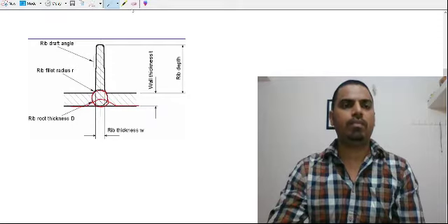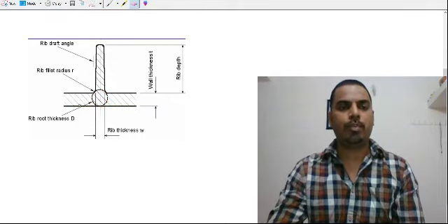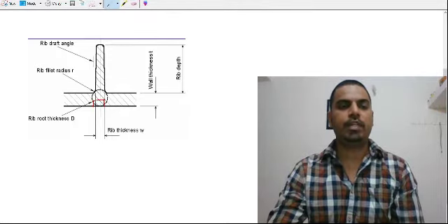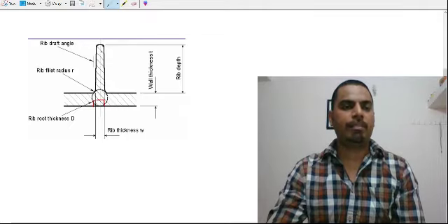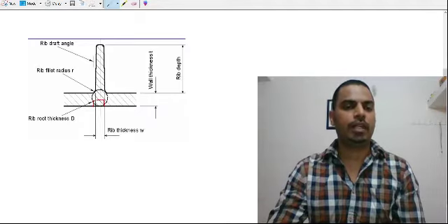One of those options is to provide a groove or a dent at this location, like this one, which is opposite to the rib location. Okay, so we can avoid a sink mark at this location to have a uniform thickness.